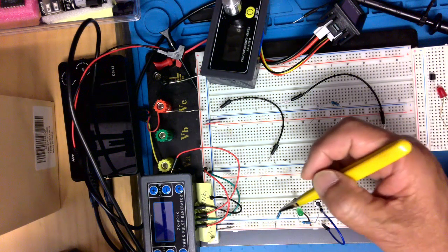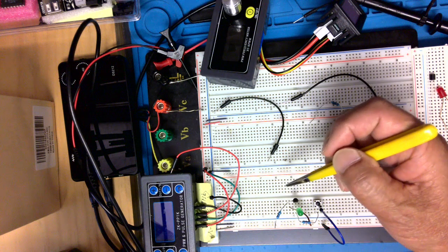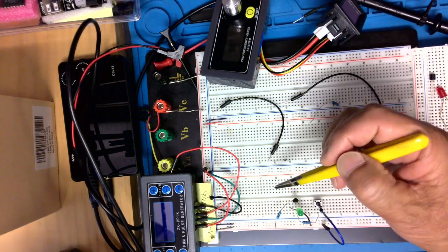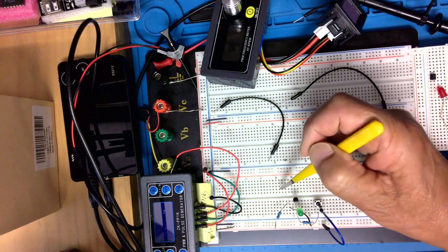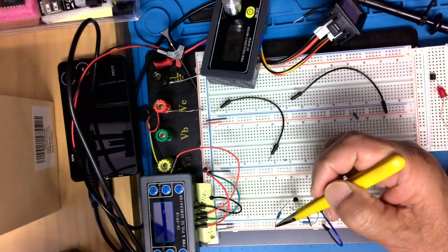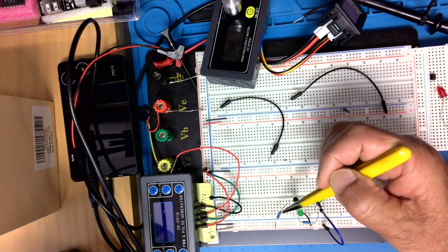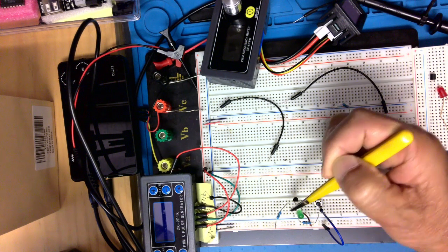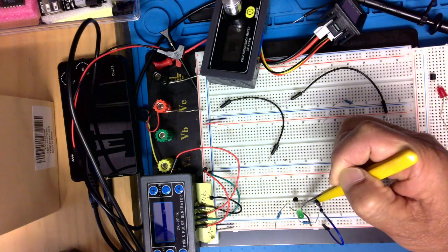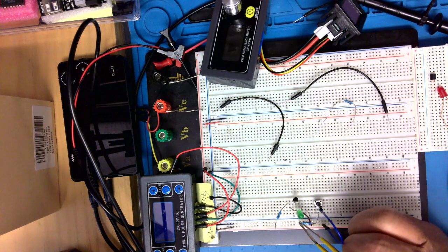Okay, we built a simple transistor logic gate. This is an inverter. So this is a transistor here. The collector is connected through the load resistor to the 5 volt, and the LED is across collector to emitter, because the emitter goes to ground, and the base in the middle is picked up here.